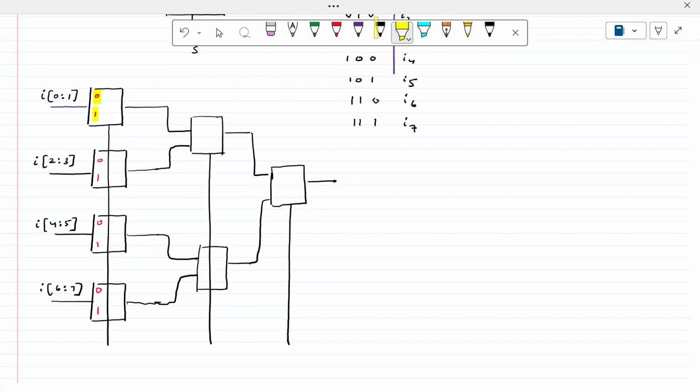For example, if you have a multiplexer, something like this, here is A, here is B. So that means 0 stands for first variable, 1 stands for second variable. Whether the first variable or the second variable is selected is decided by the S. If S is equal to 0, this is selected, and the corresponding bit will be transferred as output.